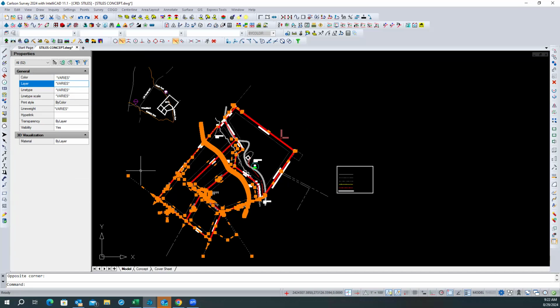Maybe I should put it on a different layer. Well, here's what to do. Hold the shift key now and go up there and cross the ones that you want to keep. Well, yeah, see, because when you shift select, you deselect. Now that means it has to be entirely within. If you go to the left with your window, it will be a crossing. Yeah, like that. Okay. And go down and get another little piece there in that middle.